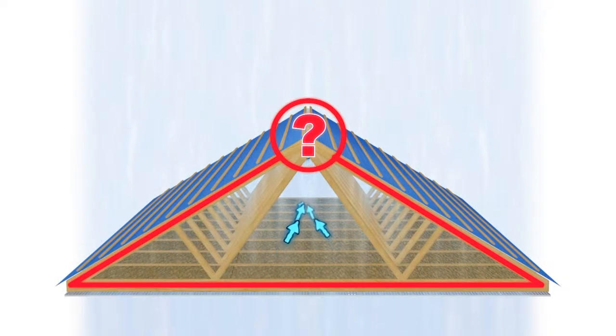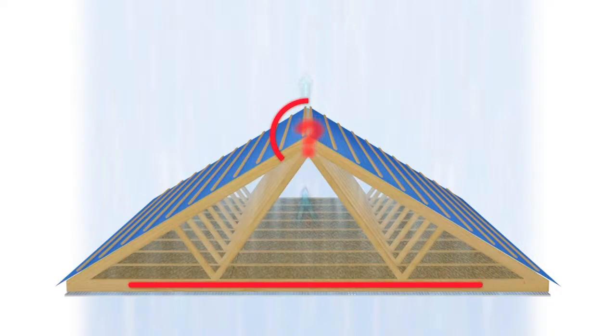Given the various categories and differing guidance for ventilation, and the lack of clear specification advice for more complex roof types and shapes, a simpler option is often to omit the ventilation altogether and rely instead on the vapour permeability of the underlay to remove moisture.